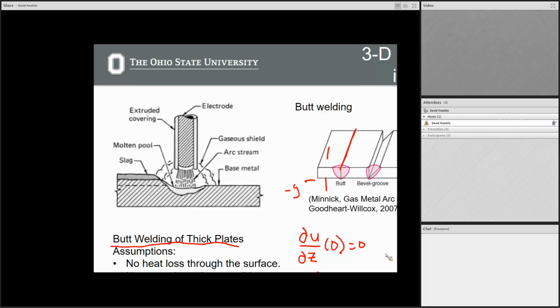Okay, so is that going to be a heat loss by convection to the environment, or a heat gain? Right, that would be a net heat loss. Convection is basically the spread of heat through some sort of medium flowing past the surface, and that essentially, for lack of a better word, convects that resident heat to a different location in space.